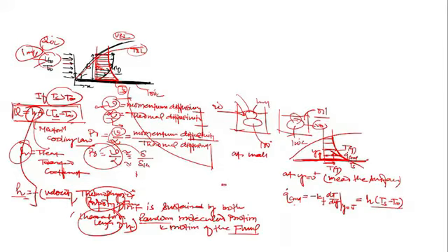And is h a property of the fluid? Tell me please, is h a property? No, it's not a property. But all the complexities of convection heat transfer are involved in h, because this h depends upon a number of parameters. Yes, it depends on the properties: viscosity, density, thermal conductivity, specific heat capacity, characteristic length, and also the velocity of the fluid.